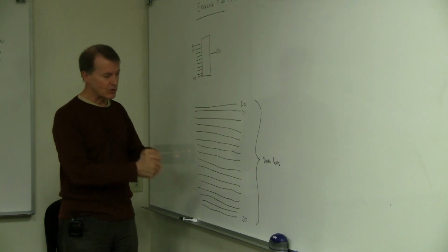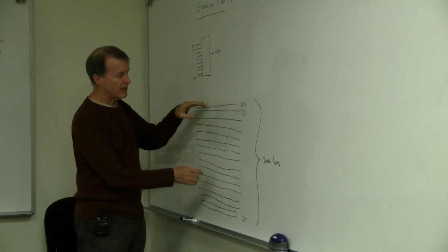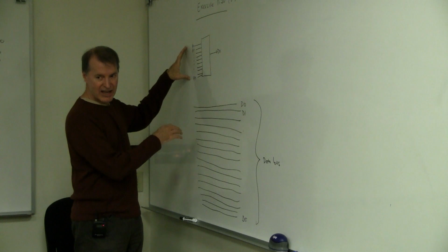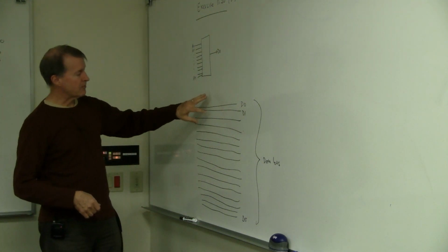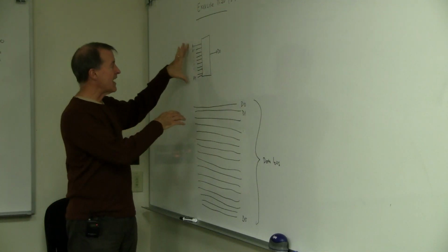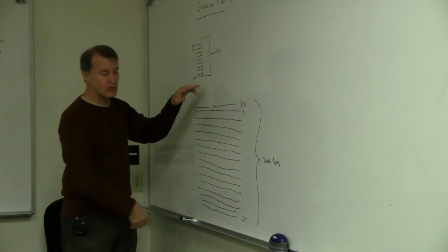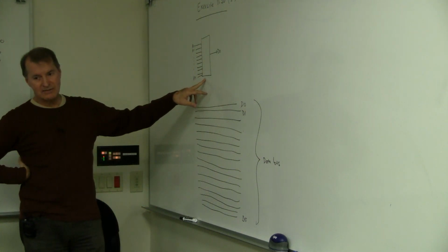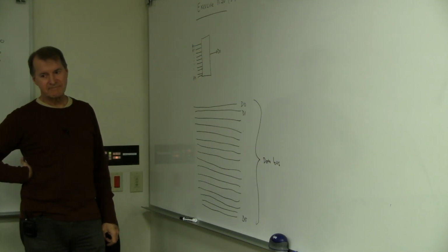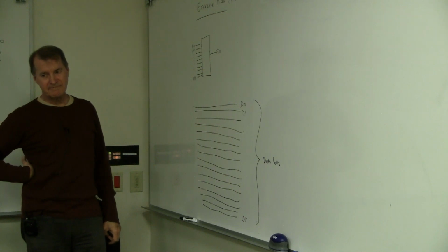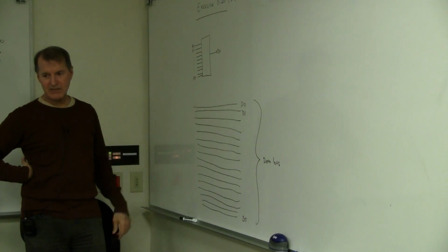Are you with me? So if the data bus is 16 bits wide, then the address that gets put in is the address of the first byte, and the next byte is that address plus 1. What that means is that for any address, you have to have a device hooked up to every single one of these 16 lines. So how many chips is it going to take? 16. Okay, so that's the part that I understand. It's the part where it says, what is the smallest number of bytes of memory this computer can have? Well, figure out how many bytes of memory that is.